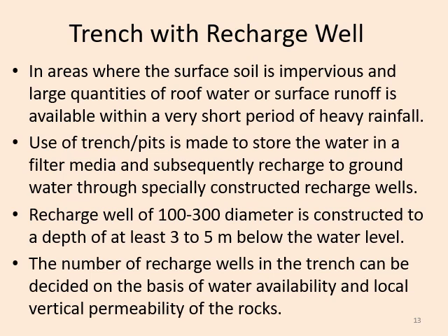So use of trench or pits is made to store the rainwater or surface runoff in a filter media and subsequently recharge to groundwater through a specially constructed recharge well. So here, not an existing tube well, a recharge well is specially constructed, and before that a trench or pit should be there.